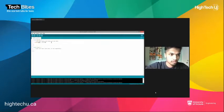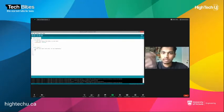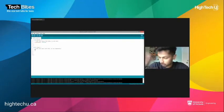So you write OUTPUT, and in the loop code, as the name suggests, it is an endless loop. Whatever bunch of code you write here, after executing all of it, it again starts from this point. So for now, I write code so that the built-in LED is on for 1 second, and then after 1 second it switches off for 1 second.